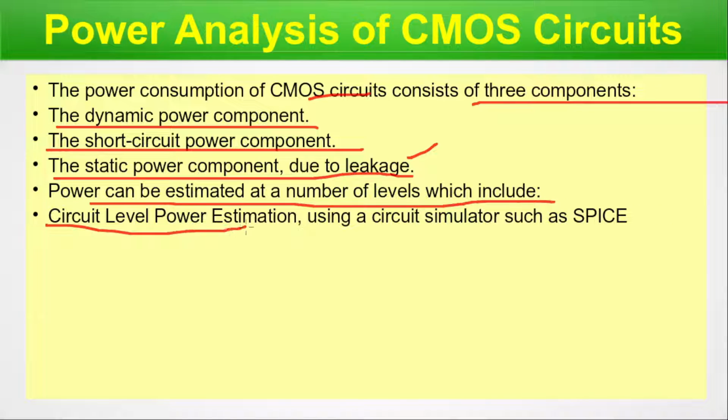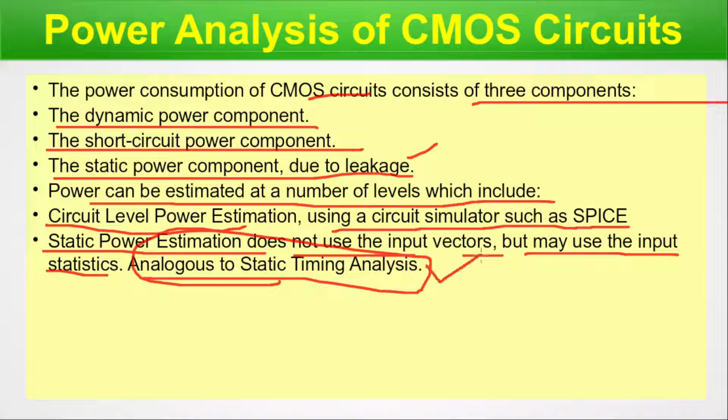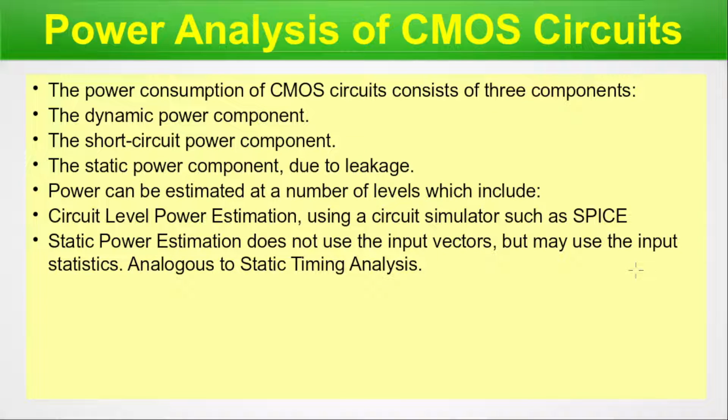Circuit level power estimation using a circuit simulator such as SPICE can be done. Static power estimation does not use the input vectors but may rather use input statistics, which is very similar to static timing analysis where everything is static. So there is a basic difference between a static analysis and a dynamic analysis. In dynamic analysis, everything has to be simulated live with respect to time.